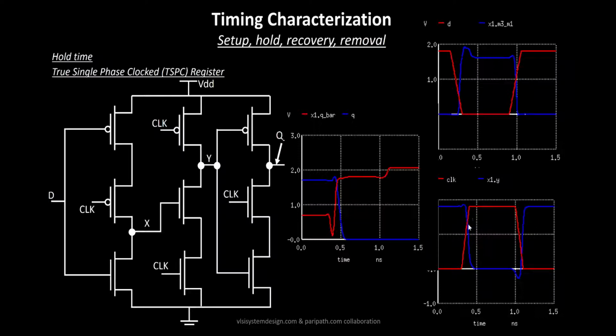For example, now your clock goes to rising high. Whenever your clock goes to logic 1, this particular thing stops behaving as an inverter. Your X has been held at logic 1. The voltage at the X node stays at logic 1, and a couple of more things happen. Your clock pin is at logic 1, so this transistor turns on. This is already turned on because the X input is logic 1, and as a result, the value that you see over here gets completely discharged.